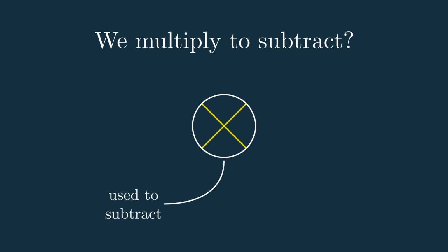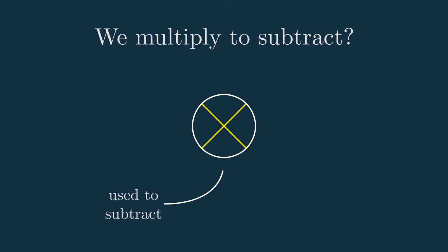This is seriously one of the coolest RF blocks in my opinion, because it's a direct hardware implementation of a basic math operator, which, as you can probably guess from the symbol, is multiplication. And this is how we achieve the frequency subtraction to get the beat frequency of our target. So we multiply to subtract? Yes, and this is more clear if we look at our two signals for what they are, sinusoids, which is just a collection of sine waves.